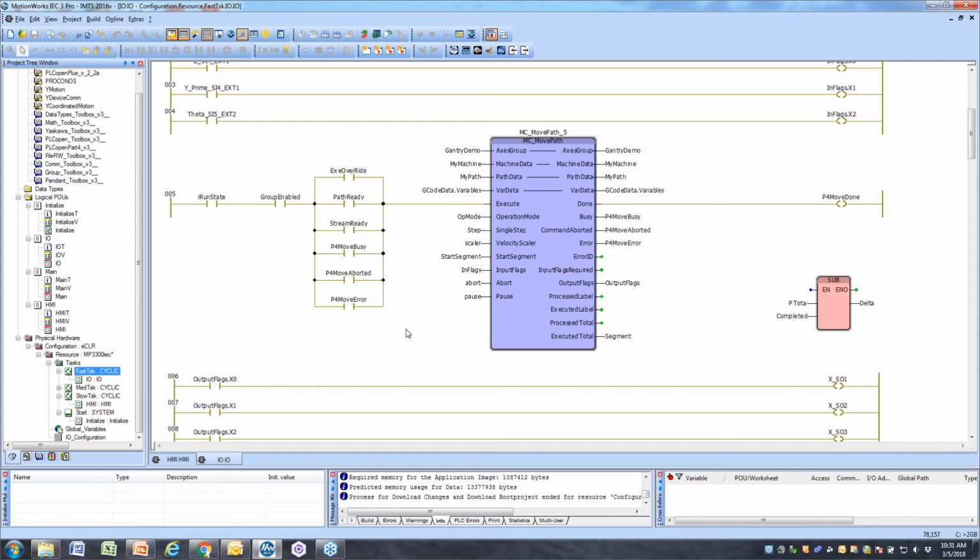That all depends on the data you're processing, and if you have a motion path that has generally large distances between segments, it's not necessary to run this block this fast unless you were controlling outputs along the way. That would be the one major factor in determining where this block is best suited, because it will monitor for the current live motion segment and then be able to track and set the output flags appropriately, and that is more accurate, of course, the faster this block scans.